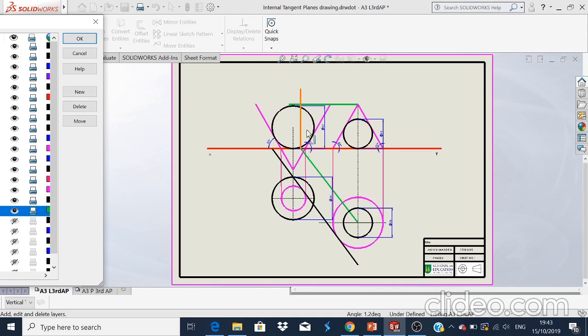This then, the next step, is we bring a vertical line upright, so we don't know how far yet, and we bring from the apex of the cone a horizontal line across. Where the two of them cross, we mark that with a dot. For the vertical trace then, we join where the horizontal trace meets the XY all the way up to where these two lines intersect, and that is our VTH. So you can pause the podcast there now, and students can catch up with this.